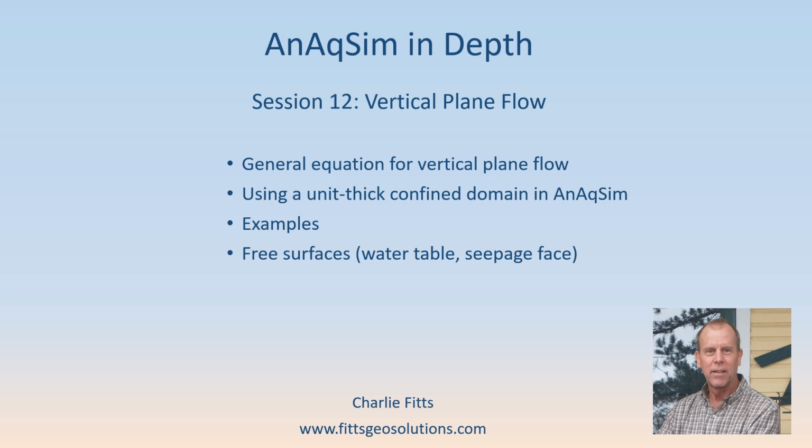Hello again. This is a relatively short session where we go through vertical plane flow simulations in Anaqsim. And it's a handy feature. It's not explicitly a separate kind of input or anything. You make use of confined domains and set them with a unit thickness, and it works quite well. I will go through several examples of vertical plane flow models and also discuss free surfaces at the end.